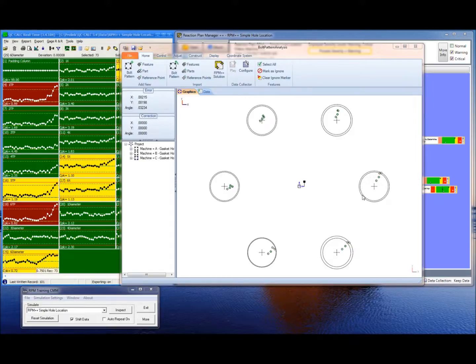The inside circle here represents the true position tolerance zone scaled up, so you can visually see it. You'll notice there's a second ring around the true position tolerancing zone. That second ring represents the maximum material condition. If you include the diameter information with the analysis, it will calculate the minimum maximum material condition. So it'll buy you a little bit more tolerancing if that's a requirement on your print.